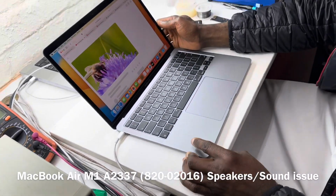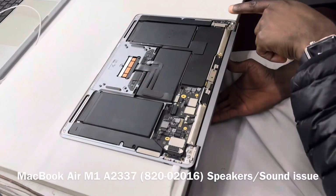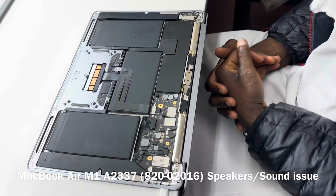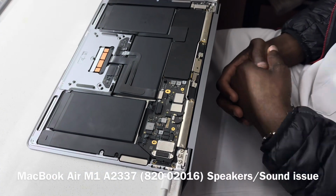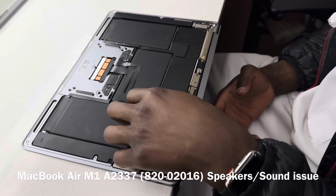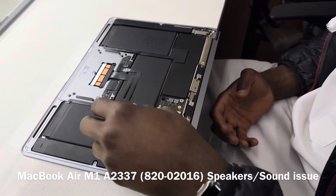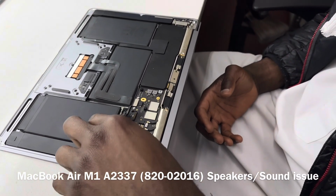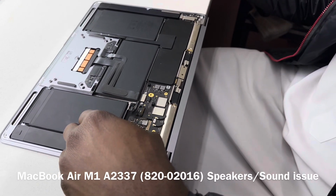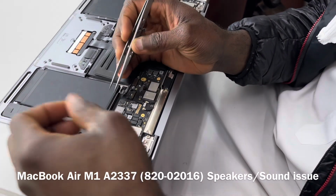So what has already been done to this machine is this. The audio board, which is this, and the audio cable has been replaced, but the issue still persists. So the next thing we want to do is take the board out and work around to see what exactly is going on. So this is M1. And another thing that I did mention is because we are getting sound in this manner, it also means that if you are to connect headphones to it, you will also get sound.